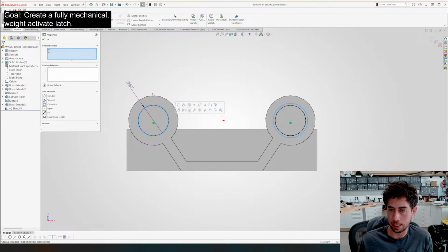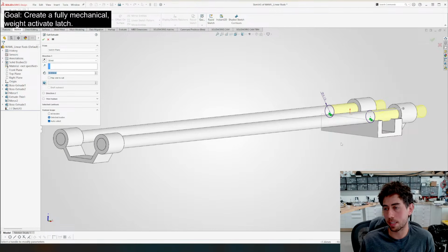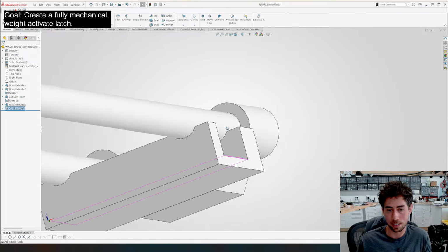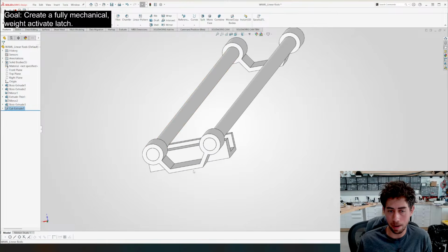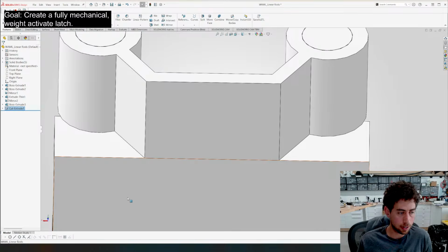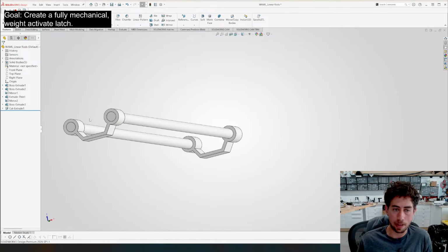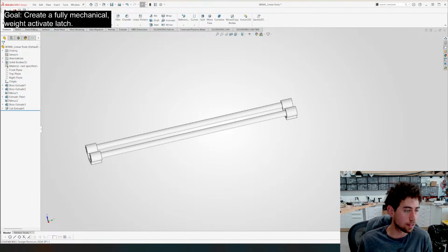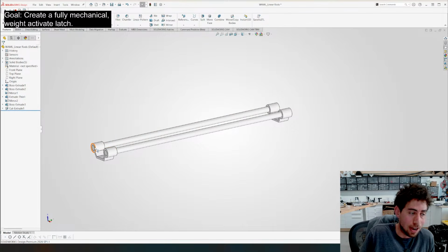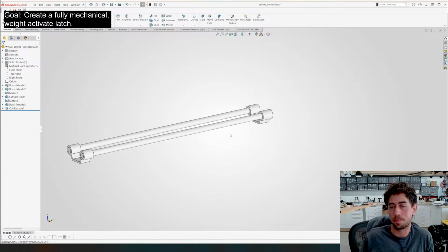And these are just tolerances that I'm baking in based on experience. Basically, I just want to make sure that if I'm latching this in, it's not going to be interfered with by, see, like this. So this part, and we might as well do the screw-in components here while we're at it. The drop is arbitrary. Basically, I can make these rods however long I want. And I'm going to use these two components to make sure that they're parallel. You do run into not-parallel situations, but I think that this will be fine.